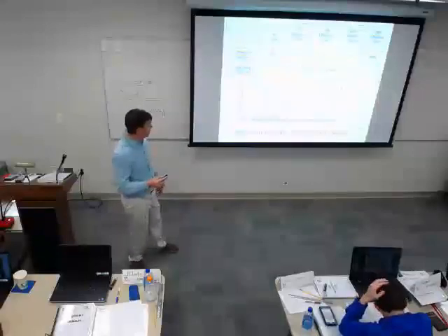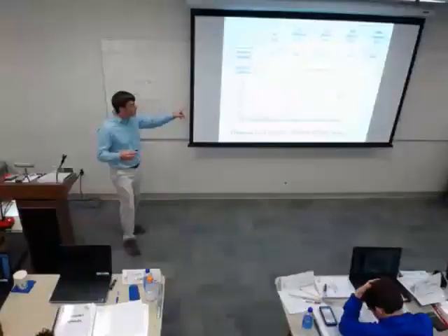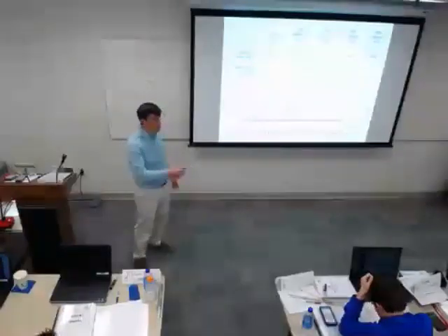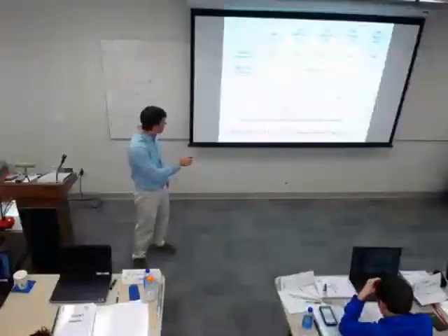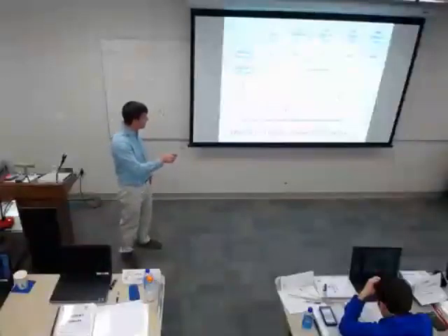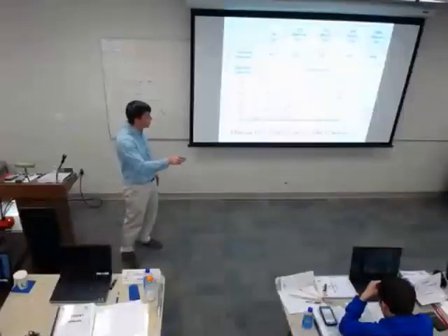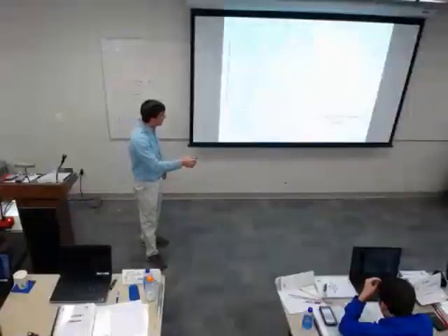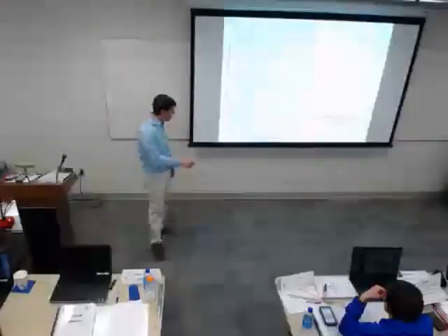You may do an example of this in your lab. Basically, what you want to do is, let's say I'm going to have only 25% of whatever my duct is supposed to be. If I know my blast area, my outlet area, I'd have to have fan data. I'd have to have my submittal to know this information. Say I'm at a 0.7 and I'm only going to have this much duct. I come up with a U to V, and I go look at another chart and I find U to V here.